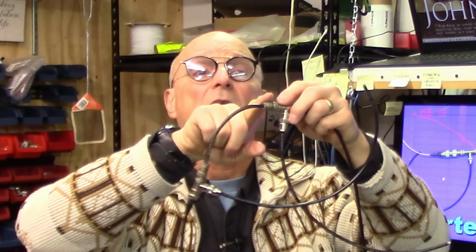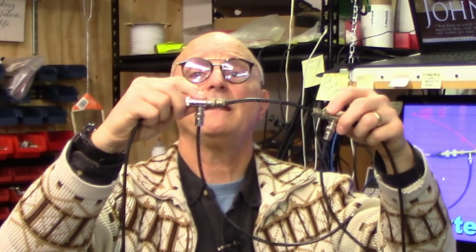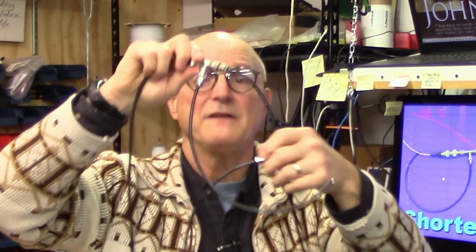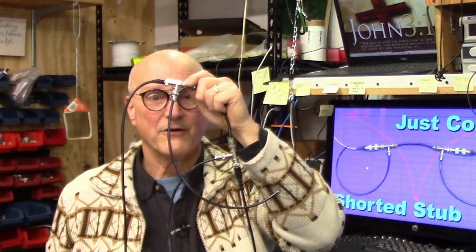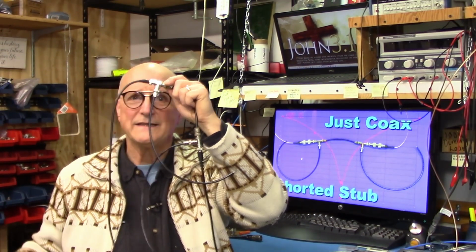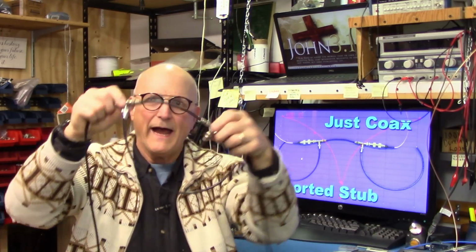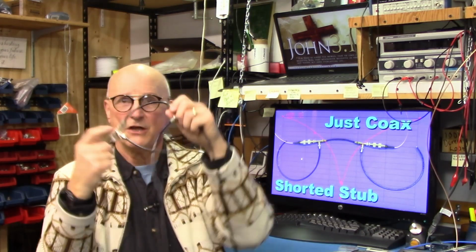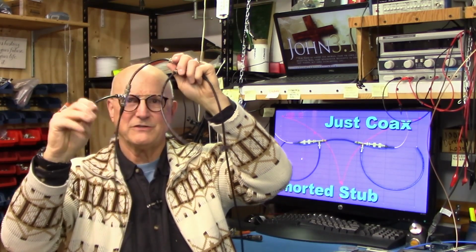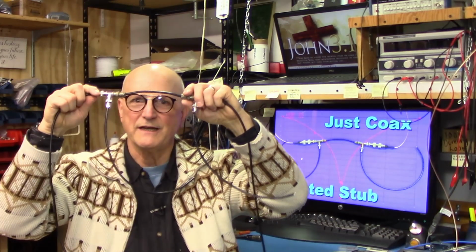So we have a high impedance coming into this T, we have a low impedance at the T because of this stub, and with a voltage divider, high impedance in, low impedance out, we significantly reduce the voltage of the signal at this second T. And this is true here just as well. By adding this second T, I now have an attenuation of 70 plus dB at the frequency in question, assuming that we can perfectly tune these stubs to the same frequency.